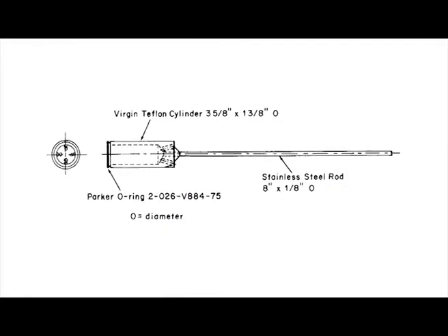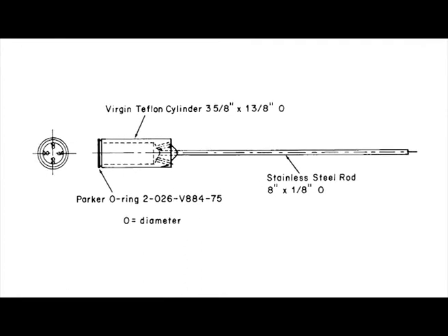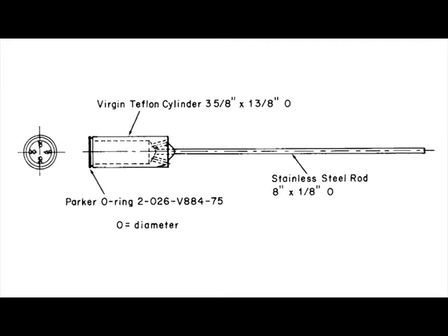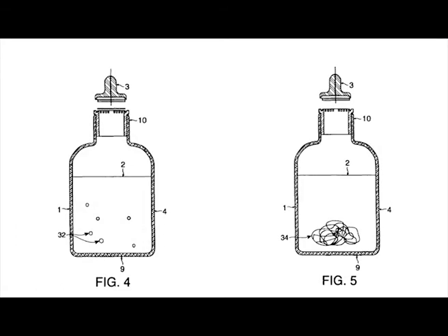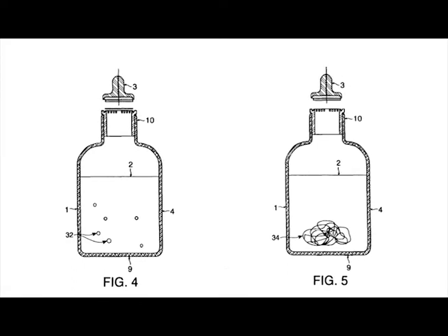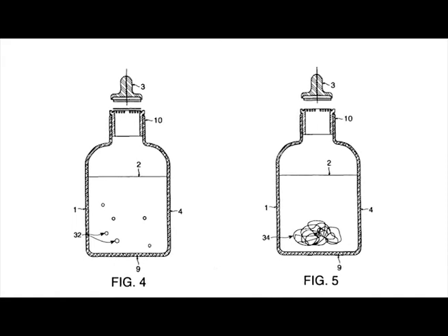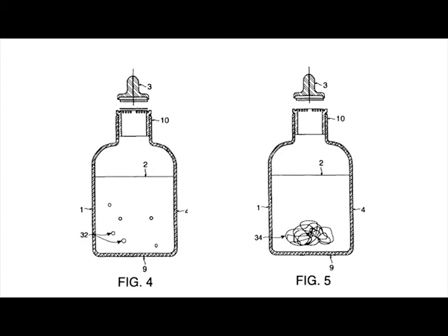Apparatus 7, reciprocating holder. The assembly consists of a set of volumetrically calibrated solution containers made of glass or other suitable inert material, a motor and drive assembly to reciprocate the system vertically, and a set of suitable sample holders. The solution containers are partially immersed in a suitable water bath of any convenient size that permits maintaining the temperature inside the container at 32 plus or minus 0.5 degrees C.